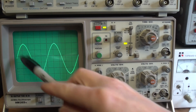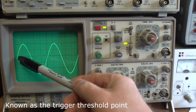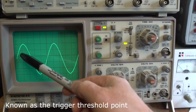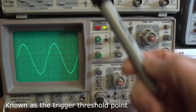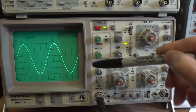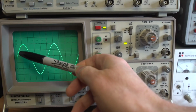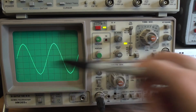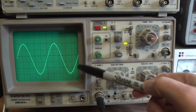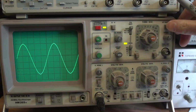You can have a positive trigger or a negative trigger, and it's looking for a certain point where the voltage gets to, for argument's sake, let's just say it gets to 1 volt. And when it gets to 1 volt, it starts the trace. Off it goes. And then when that's gone off the screen, it waits until the signal gets to that trigger point again, and so on repetitively. So every time we see a trace, it's being locked by the trigger. And I can show that if I turn the trigger off.